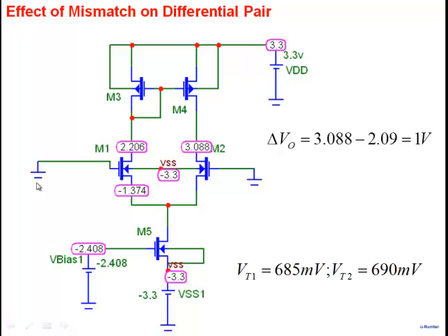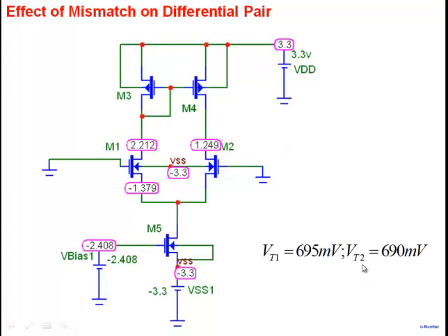Now, when you attach a source here of 5 millivolt, what does it do to the output? It gets amplified, right? And what is the phase difference between this and this? 0. So the effect of VT change is the same as, you can think of, which we'll see, attaching a source, a voltage at the input here. It can be simulated. And this voltage will get multiplied by the gain and will appear over here. Okay? Alright, so that's VT1 and VT2.